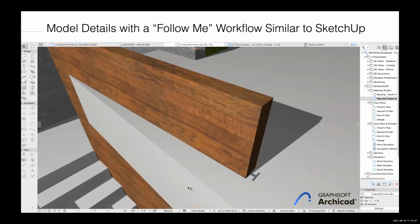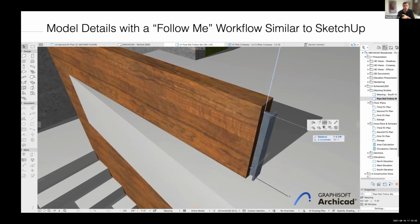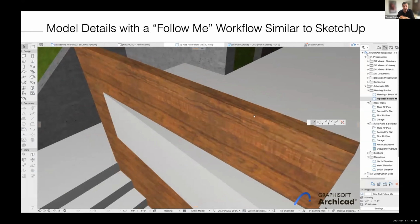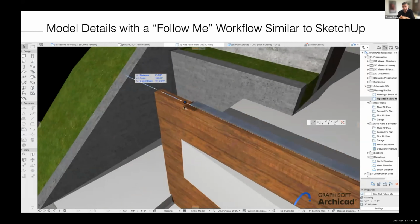One of the things that I think is also important to note, because I used to use SketchUp myself, is that the Follow Me command is a hugely powerful part of the program. And in Archicad, we can do something very similar. You draw a 2D shape, you take that shape, and then you extrude it. And you can extrude it along any shape, for example a railing or some sort of edge condition along this wall.